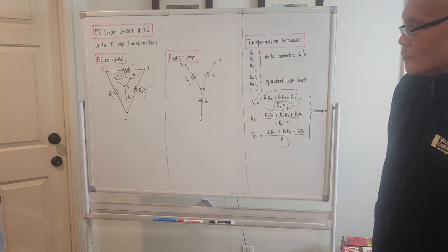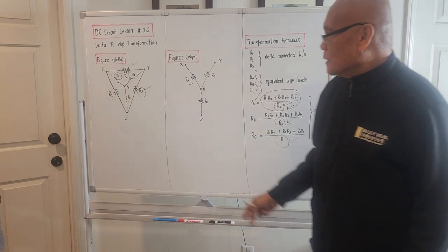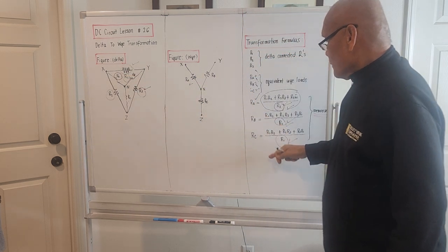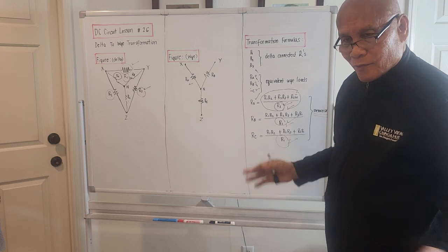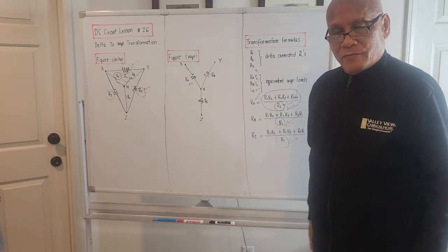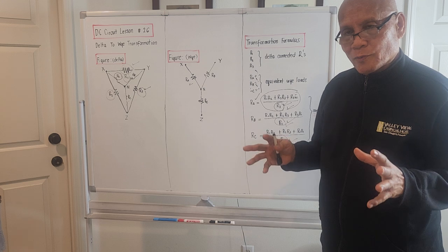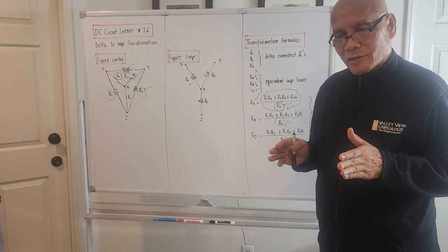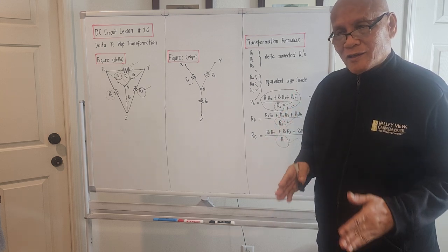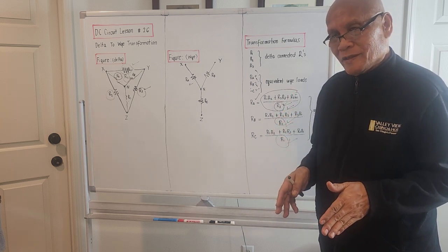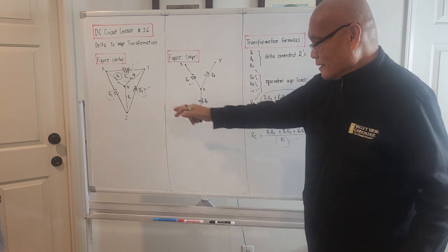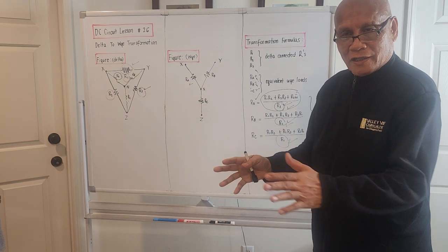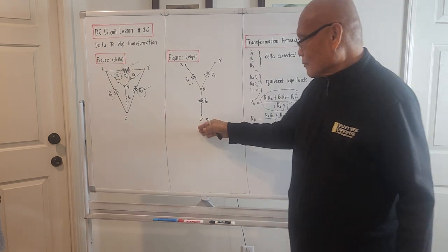So for now, we know how to convert delta connected loads to their equivalent in terms of Y by using these formulas. And I want to emphasize that the main reason why we need this conversion is to make a complicated circuit less complicated in the computation of the so-called total resistance. If a problem is asking for the total resistance of a circuit, and that circuit involves delta connected resistances or Y connected resistances, at least you will be flexible in here.